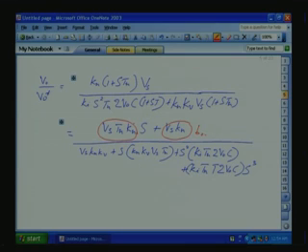If you see the transfer function, this is of the form B0, B1, then numerator, this is the A0, A1, this is A2, this is A3. So, one condition as previously, the first condition is B0 is equal to A0 and B1 is equal to A1, so we have to equate them.